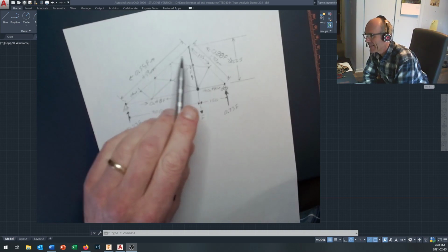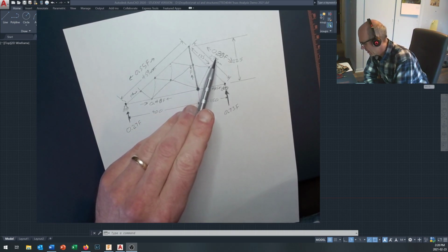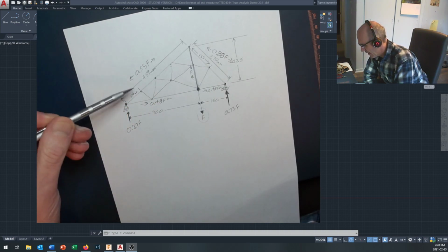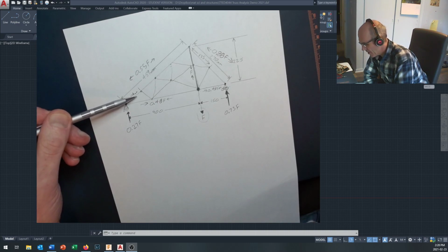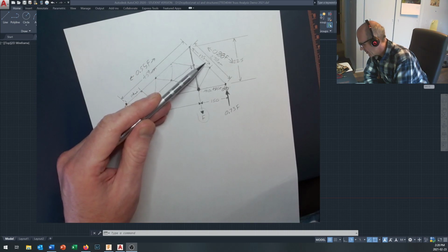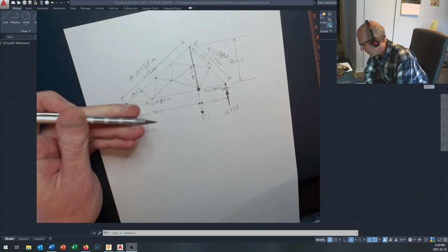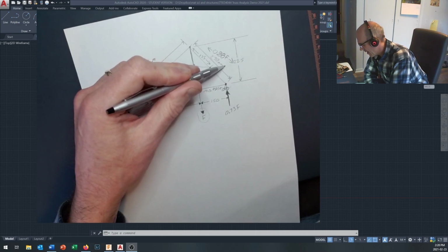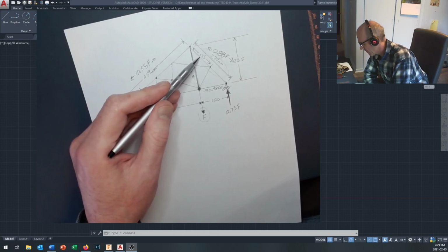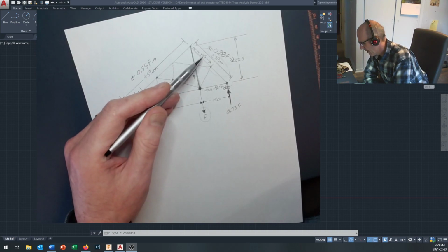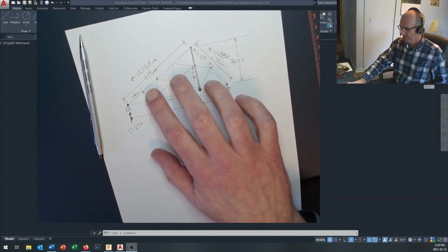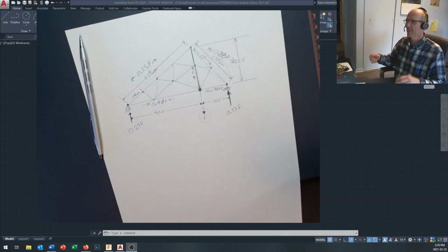Now, again, this doesn't look really good because I've got higher force running down right here than I do over here. And now these are shorter. So these are the stronger ones now, but dealing with less force, whereas this is a little bit longer. So by taking a look at that, I'm going to make a prediction that if I have a buckling failure, it's probably going to come over here somewhere because I've got a longer member subjected to more force, and maybe I should have put 2 nodes in there. Maybe I only needed to put 2 nodes on this side right here because it's not seeing as much force.